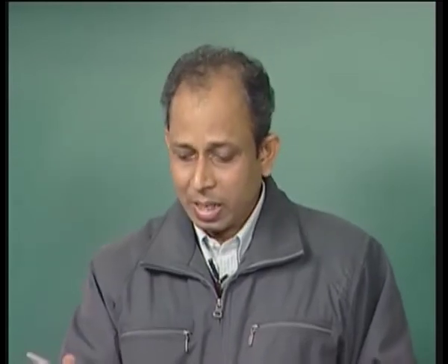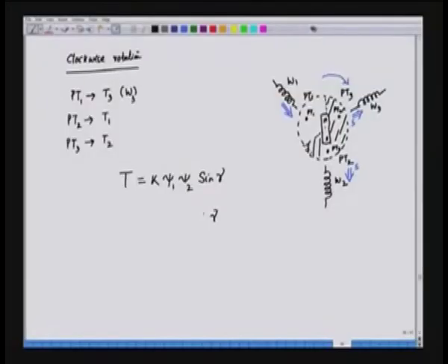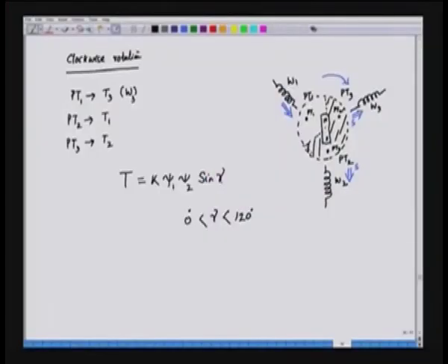Now in this case you can see that when a winding of the stator is switched on, the angle is approximately 120. So in fact gamma in this case varies from 0 to 120. Alright. So we have the expression for the torque, and gamma is not constant. We are not having any constant angle. In each revolution there are 3 switchings, because we are having 3 transistors, and the torque is proportional to sine gamma, and gamma continuously changes from 0 degree to 120 degree, and hence the torque varies as follows.